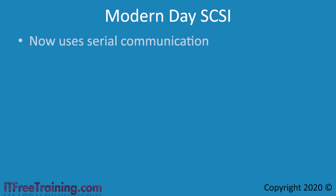Modern SCSI now uses serial communication rather than parallel communication. As parallel communication got faster, problems used to occur like clock skew. Clock skew essentially means the timing of each line would get slightly out of sync. As parallel communication got faster, it became harder and harder to keep multiple signal lines in sync with each other. Since serial communication does not have to keep multiple lines in sync, it does not have clock skew problems and thus can transmit at faster speeds.